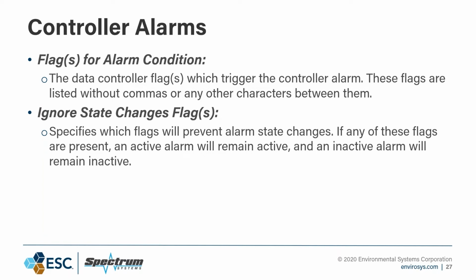For example, if your technician is doing maintenance, he can throw the M flag on the data, and the alarm won't trigger if you have that in the ignore state. And that's useful when they are doing maintenance or maybe even the calibration.